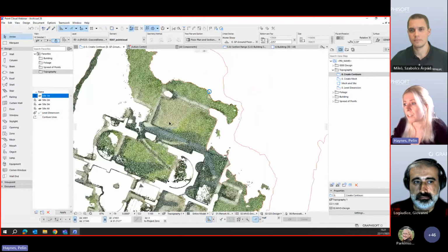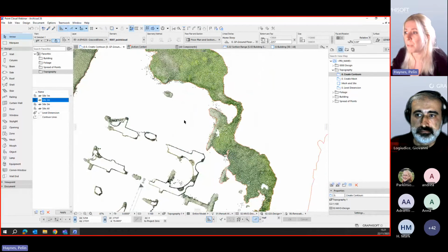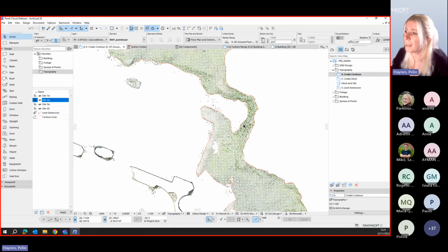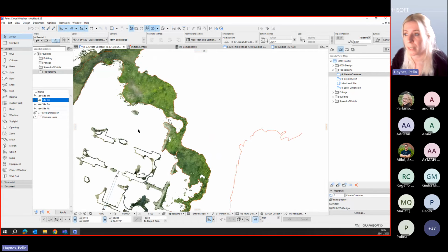If I keep highlighting the same side and change to 2 meters, you will see that at the bottom, my contour line on 1 meter is still following what I see on my screen, but then I will have more points on my screen, which I will again follow with the next contour line to represent my 2nd meter.